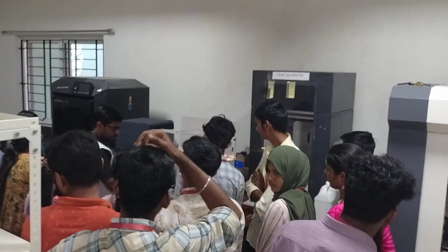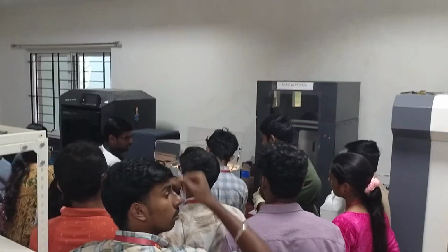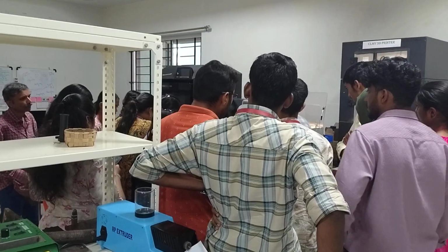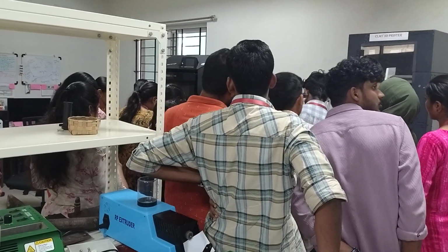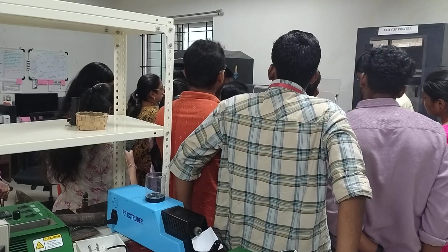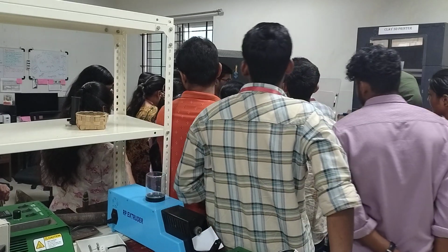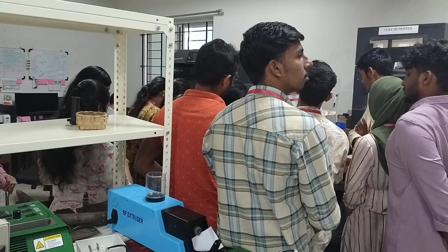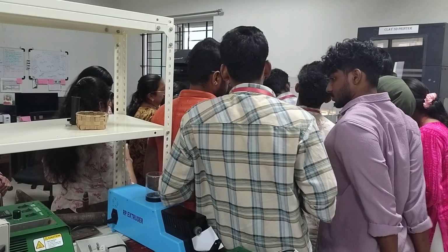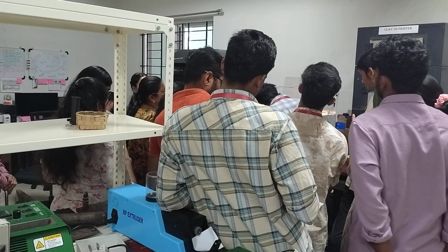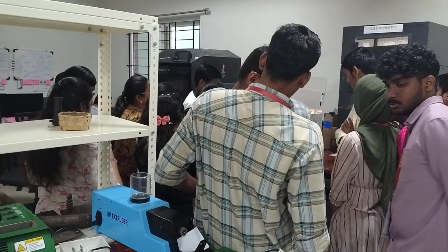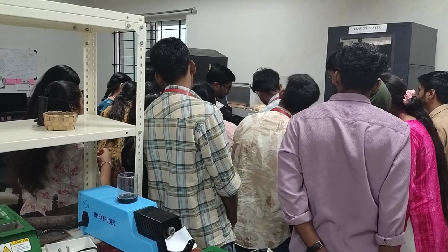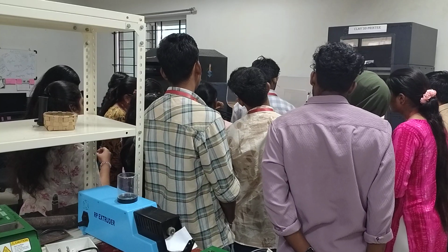I have tried to get back. Okay, since the extrusion has not happened, I'll click on retry. Repeat step. Yes, so now the filament is coming all the way and it goes to normal. For this you have to be a little bit ready and cautious that when it starts coming out, you have to click on stop. So a kind of tick sound will start coming. Yes, stop. So now our filament is coming from here. Our fiber is loaded.